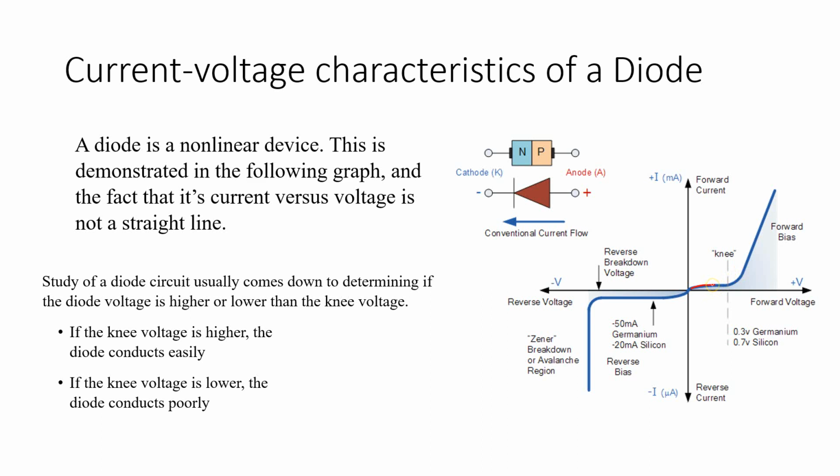So up to a point where you now have enough voltage, which can be either 0.3 or 0.5, depending on the material you're using, you're going to see a very sharp increase in the graph, which shows us that a lot more current is flowing when my voltage is increasing, which speaks volumes. That tells us that the resistance is no longer that high because current is now flowing. All of this information is here for you to read and understand. You see what I'm saying?